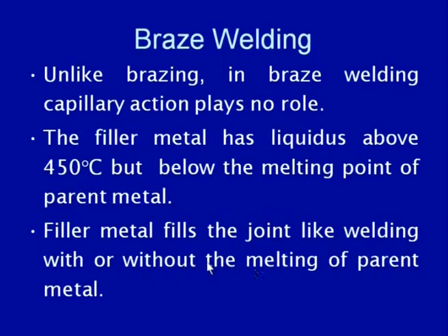Filler material fills the joint just like welding, with or without melting of the filler material. Here melting of the parent material is not intentional. However, with the application of the heat, due to careless application, little melting of the base material can take place, but it is not required for development of a sound braze weld joint.